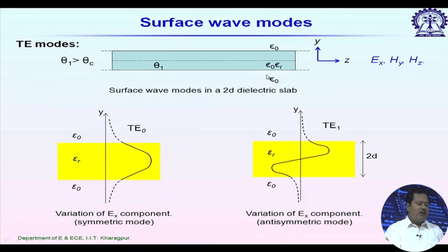So, why are we discussing the surface wave modes for a dielectric slab? We can actually design dielectric channels, which are popular as guiding structures at millimeter wave frequencies, like image guide, insular image guide, and some other forms like non-radiating dielectric, NRD guide, we will see later. For that, the concept of the surface wave modes is very important. We will be using this concept to see how those dielectric guides support electromagnetic wave propagation.